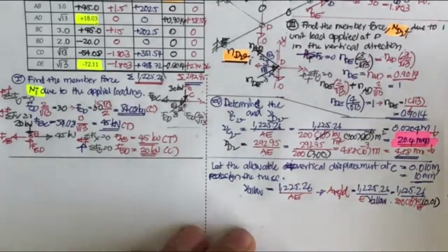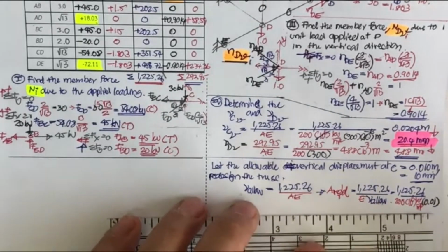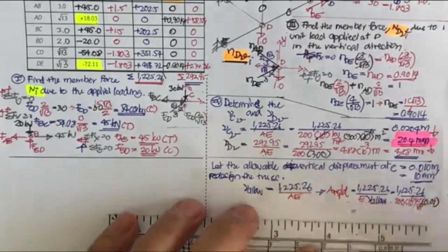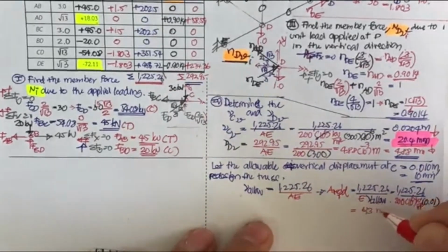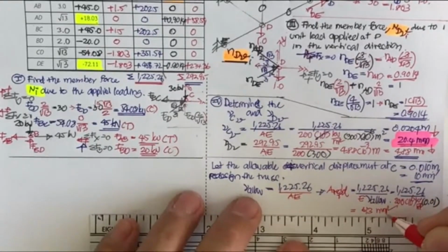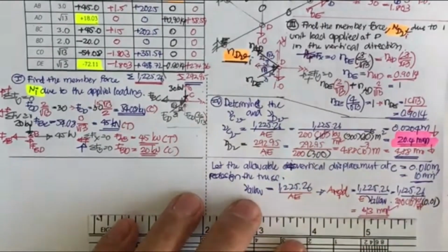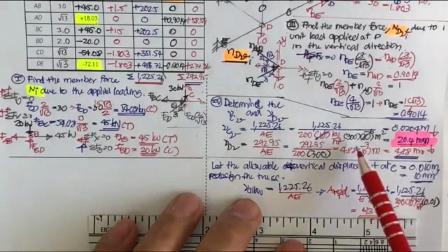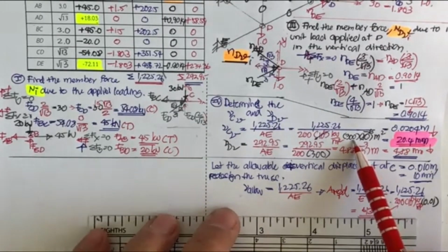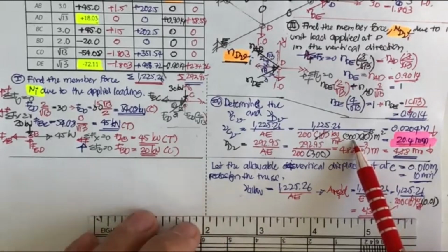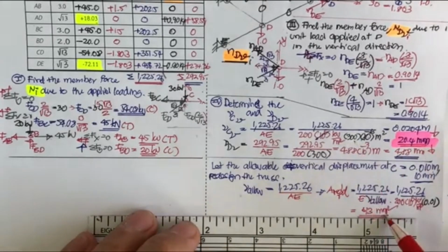If you push it in millimeter, after you do the calculation, you may get 613 square millimeter, which is going to be larger than the 300 square millimeter used here by more than 2 times.